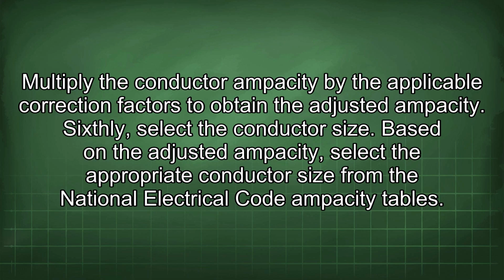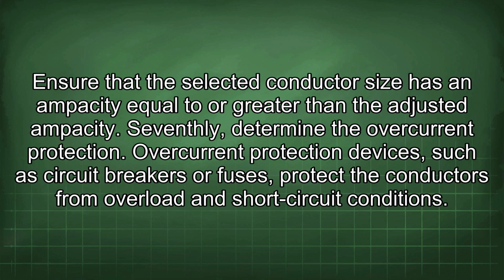Sixthly, select the conductor size. Based on the adjusted ampacity, select the appropriate conductor size from the National Electrical Code ampacity tables. Ensure that the selected conductor size has an ampacity equal to or greater than the adjusted ampacity.